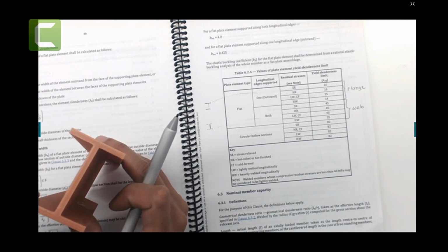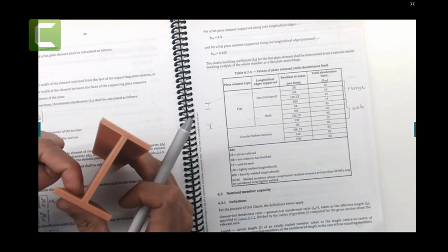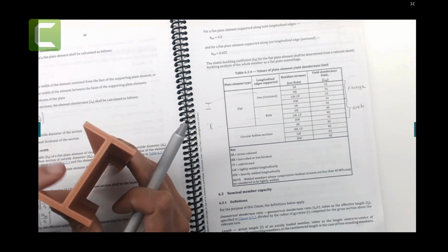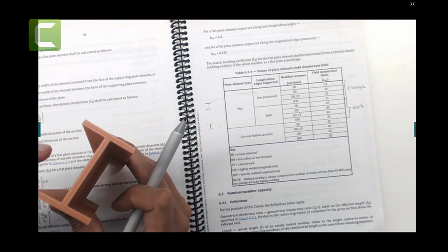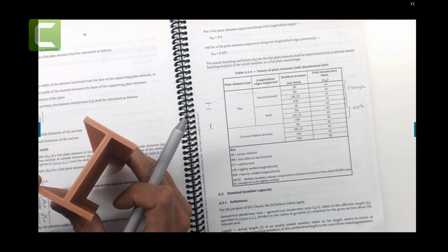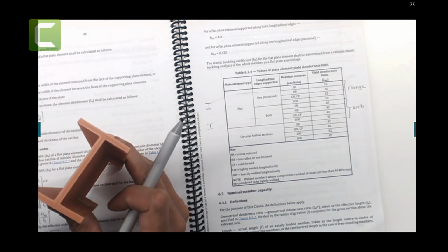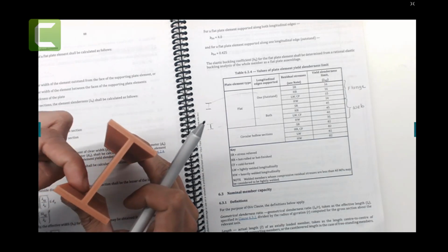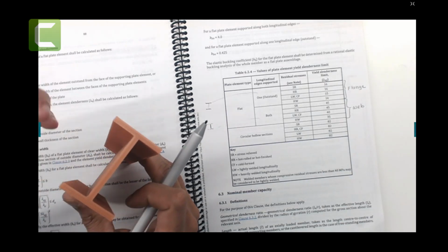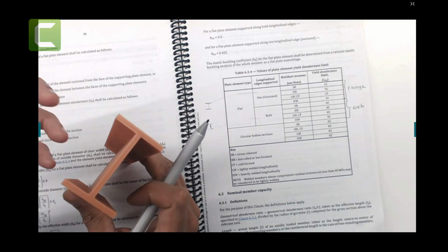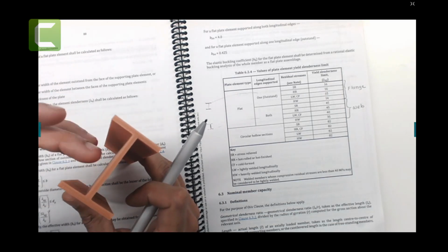For the flange, you have one edge here supported. This is a free edge. This edge is not supported. The flange has two longitudinal edges, one here, another one here. This end is free, free meaning this is free to buckle. So therefore, one longitudinal edge is supported. This edge is not supported. This edge is supported because supported meaning it's connected. In the general sense, this point is connected with somewhere. This point is not connected, it's free, this longitudinal edge. So therefore, you have one longitudinal edge supported.